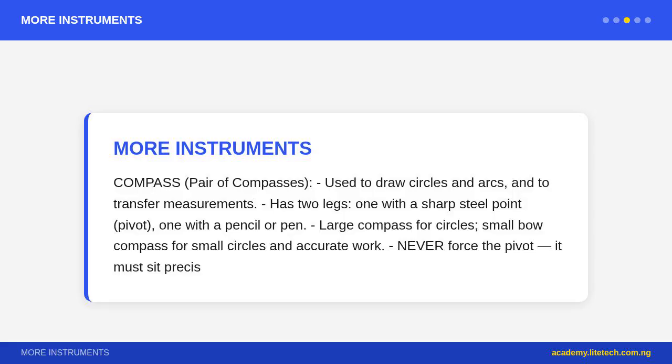Setting square for parallel lines. Slide method. Hold the T-square in position, slide the set square along the T-square blade to draw parallel lines at an angle. Proper care of instruments. 1.